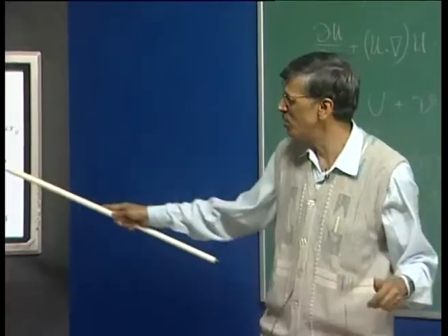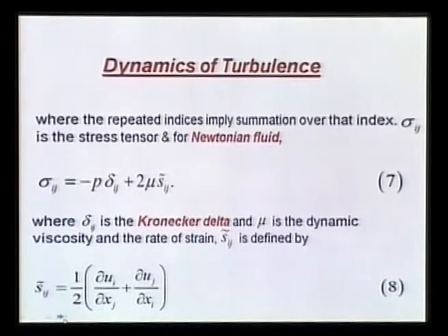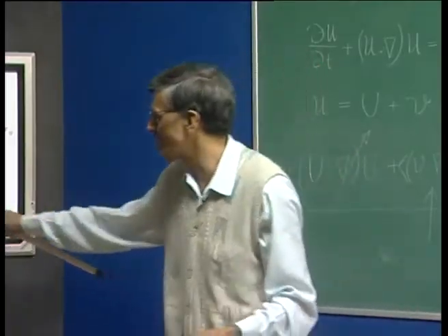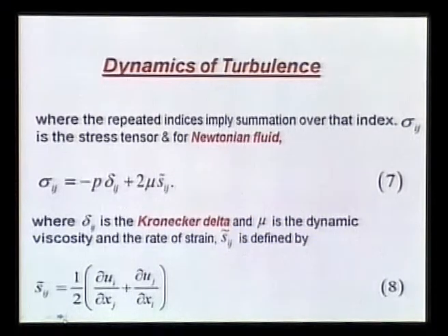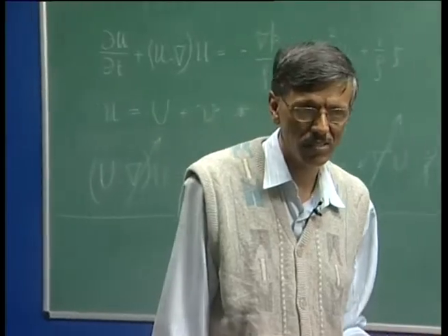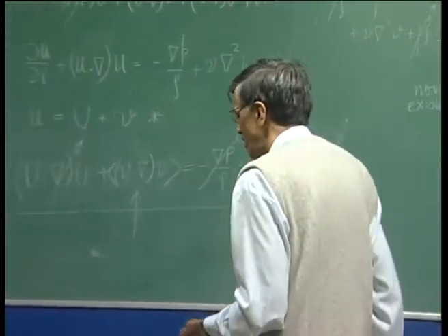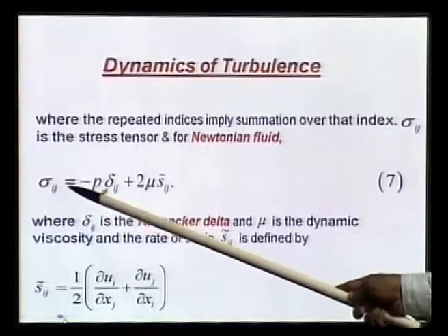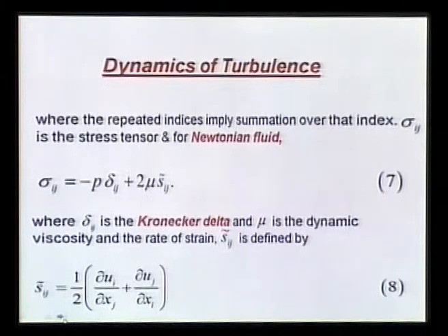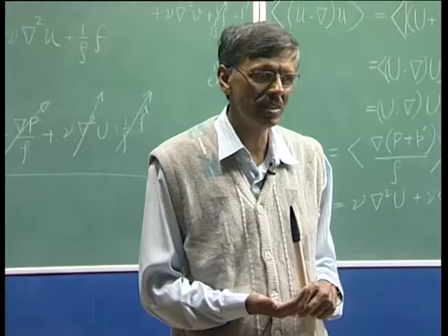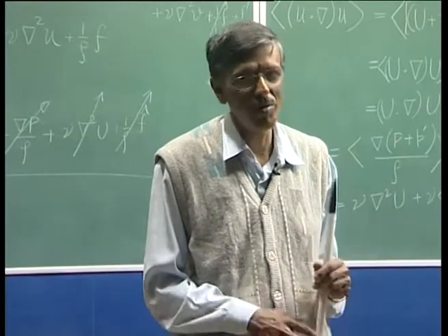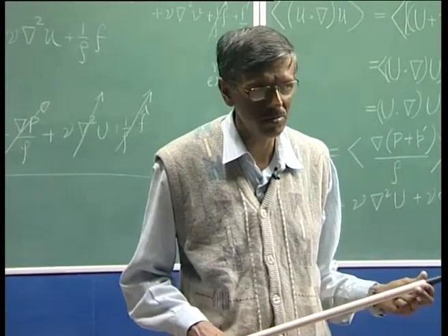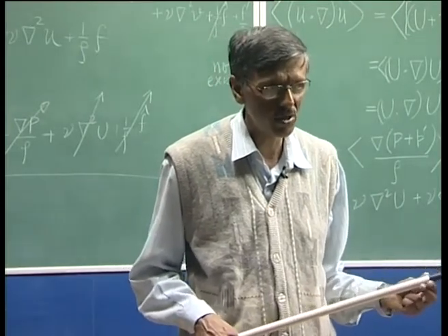It is not. There is a very beautiful theory developed from the theory of elasticity, which talks about how to relate stress and strain, and this is what is called the constitutive relation. Constitutive relations are necessary to propose a relationship between stress and strain, and in developing them you can invoke certain properties, some of which come naturally for physical variables, such as symmetry and isotropy.